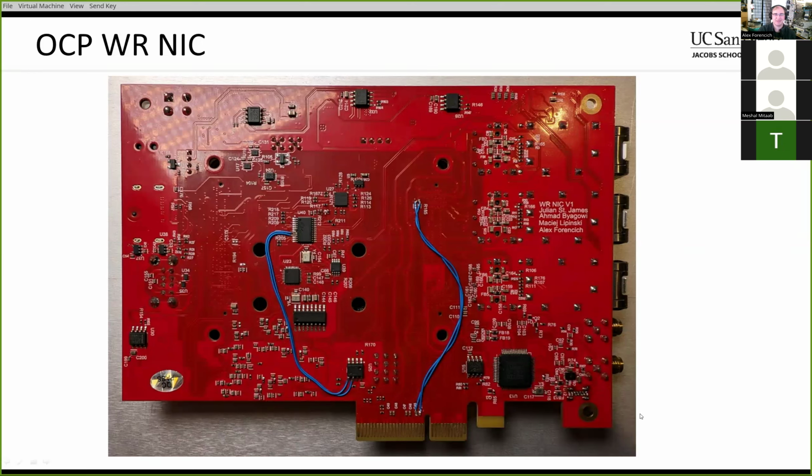So, the other thing is that the wiring for the JTAG connectors was screwed up. So the JTAG connectors didn't work, but fortunately the FTDI part, once I turned around this regulator, did work. So I have actually been able to program this thing and test it out, and I've tested all three of the network interfaces and the PCI Express interface, and all that seems to work so far.